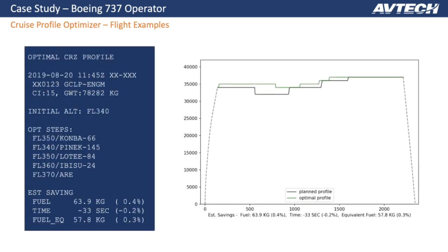Next flight is a nice one. We see it's a fairly long 2,400 nautical miles flight. We can see that the two profiles have a very similar shape, but that the filed profile is including roughly a 500 nautical mile step down. But the optimal profile has a similar shape, but it's moved. So we should initially go for a higher altitude. Probably the weather forecast has shifted at the time when the aircraft is reaching the segment of the flight where there are maybe favorable winds below, so really the optimum step down is later and not as distinct as the planned step down.